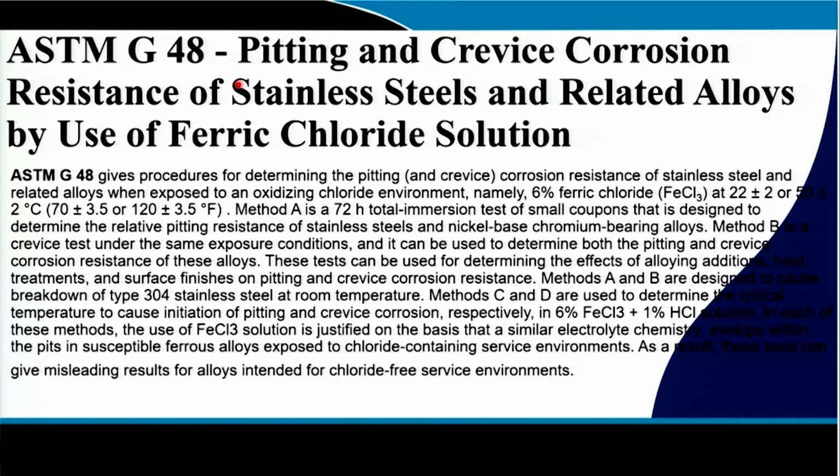Usually we saw that the alloys which undergo pitting are those alloys which have the tendency for passivation. So, when it is exposed to an oxidizing chloride environment, usually you can use 6% ferric chloride at a particular temperature, or otherwise you can also use 5% sodium chloride solution or maybe 3.56% sodium chloride solution.